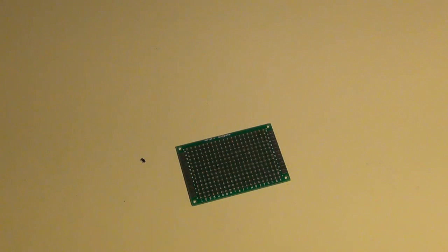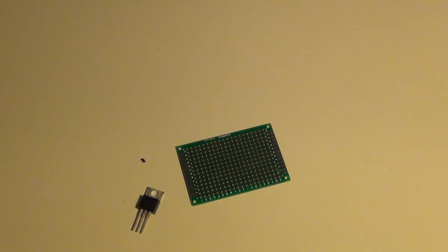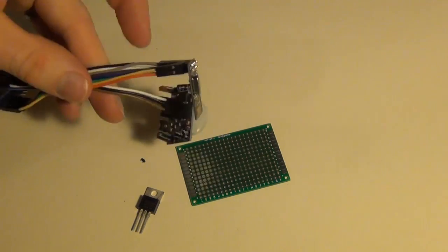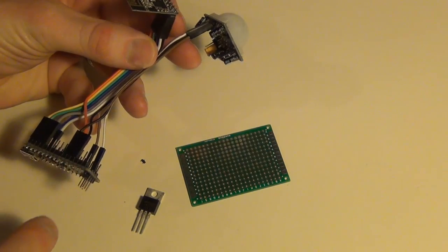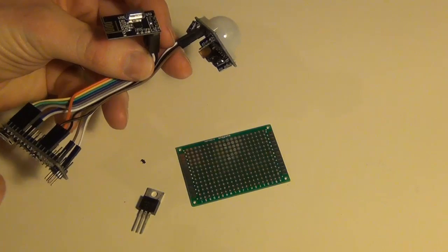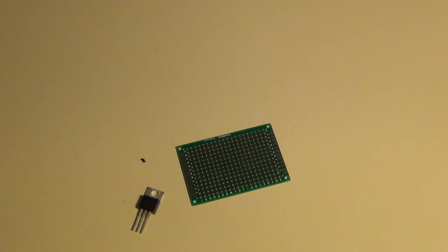Okay, moving on from checking the connections, I would say one of the biggest causes of issues that I have with my sensors is power. That may range from not having enough power or having dirty power. So power is very important for these different sensors and microcontrollers. So I recommend getting some voltage regulators to power your radio and your sensors. So whenever possible, I try not to power my sensors from my Arduino. Sometimes it looks like the sensor is powered up, but it's not getting enough power, so it'll give you strange results. Other times your radio will not work correctly or not be transmitting far enough because you have a dirty power source or not enough power from your Arduino.